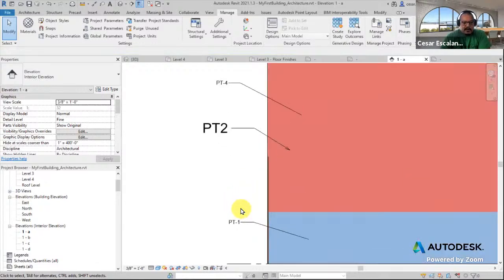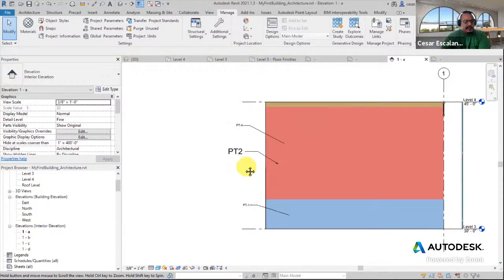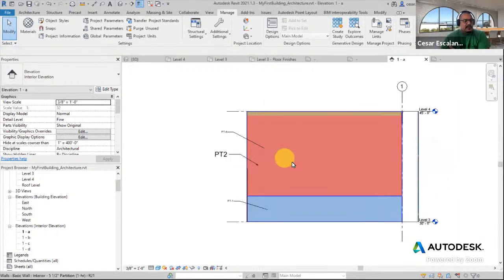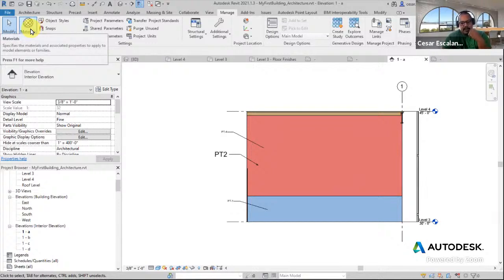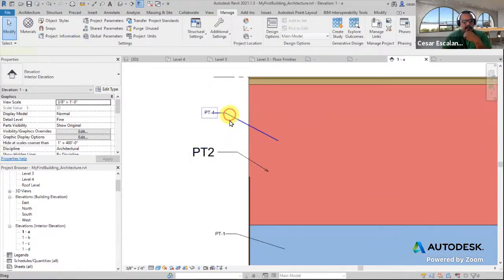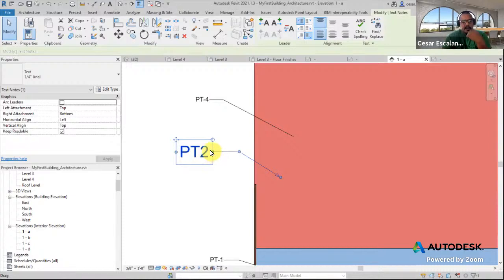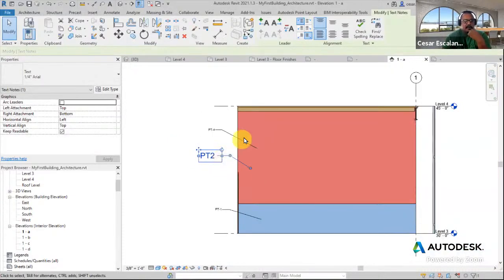All right, so I know this is going to finish. You can do this. The same process can be done for floors that have different finishes, or for ceilings, for example. When you have 2-3 different types of ceilings, it's exactly the same process. You focus on the materials, add the metadata, add the color and the projection surface patterns, and then add material labels. But yeah, take advantage of the smart tags because they are time savers for you.